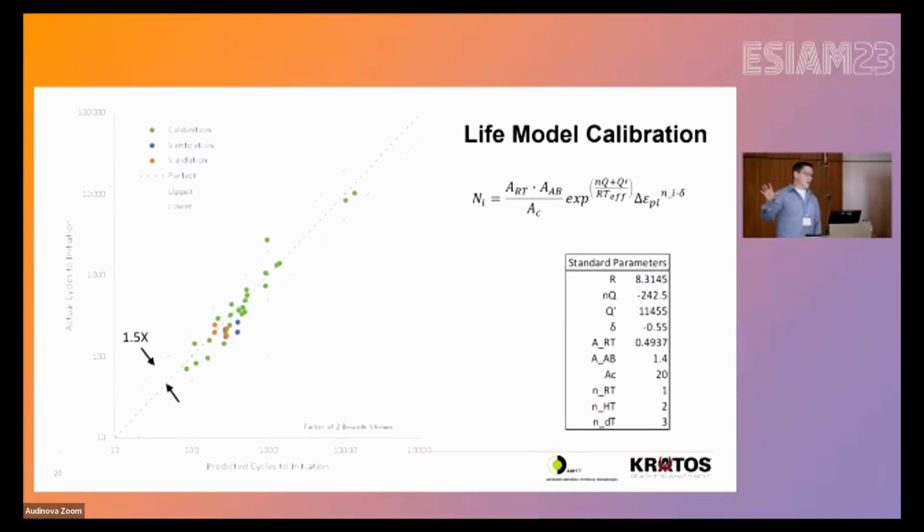Here we see the final results. So first thing you'll notice is that I way over calibrated my life model. Actual flight is very, very low cycle fatigue. But I was happy to do so. Second thing you'll notice is that our calibration data is, again, quite nice. The V&V data is okay. It's approaching the bounds of our calibration data. Not super happy about that. Nonetheless, it was sufficient to give go for very low cycle fatigue flight with these components.